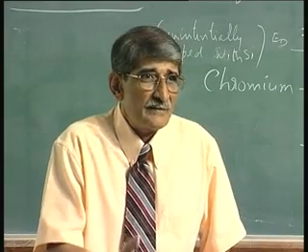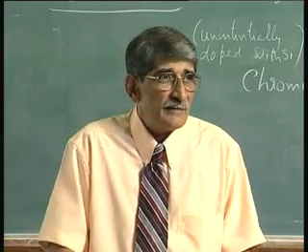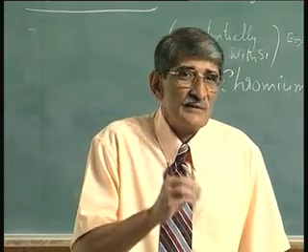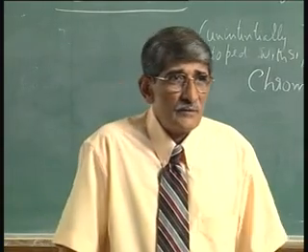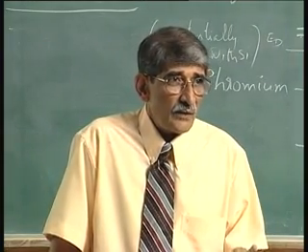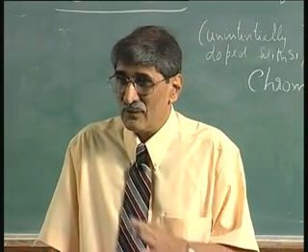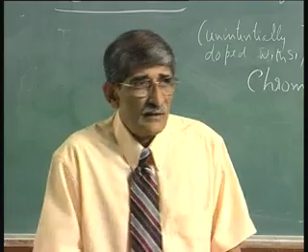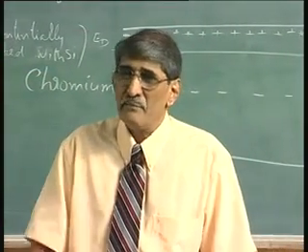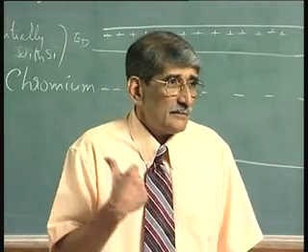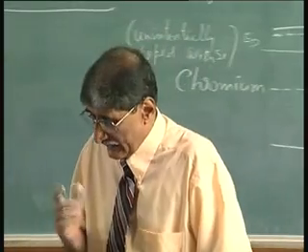You have bought the wafer with 10,000 ohm centimeter resistivity, but once you use that, the gold will move all around, it will get even into your furnace. So, you do not get good results with that. People were struggling with that. Now, today, if you want to buy a 10,000 ohm centimeter resistivity silicon wafer, you must say uncompensated, so that the vendor does not cheat you. You should say I want uncompensated 10,000 ohm centimeter p type or n type material, then he will grow a very pure crystal and give you undoped. Okay. So, this is about it.